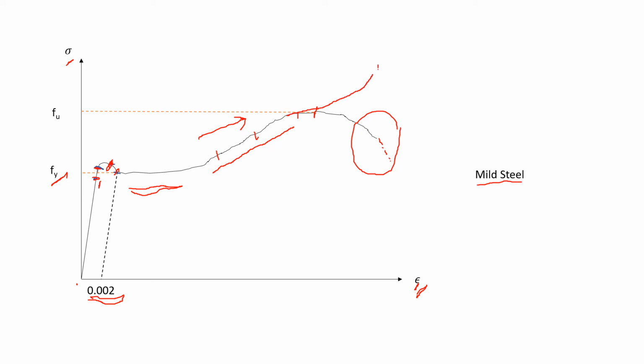We have the maximum stress at failure because the instantaneous, actual cross-section area at the time of failure is much lesser compared to the original sections. As we know, when the cross-section area is lesser, the stress value increases. That's why for the true stress strain curve we get the maximum stress at the point of failure, and for nominal it is at the ultimate point. Hope you have got the point.